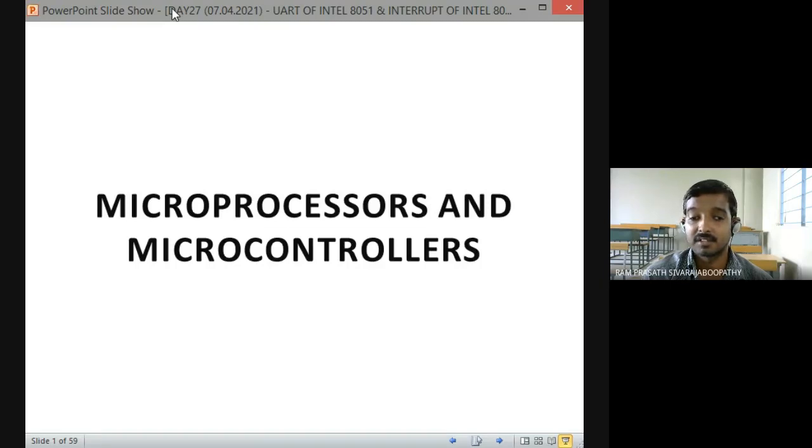Yes, as it is an up counter, it is going to increment by 1 for every machine cycle. That means if I put the value 5, the interrupt is generated after 5 counts. So for that, what have we told? We have some formula, correct? How do we have to load the count value? The count value to be loaded is equal to what? Maximum count minus the desired count plus 1, correct?